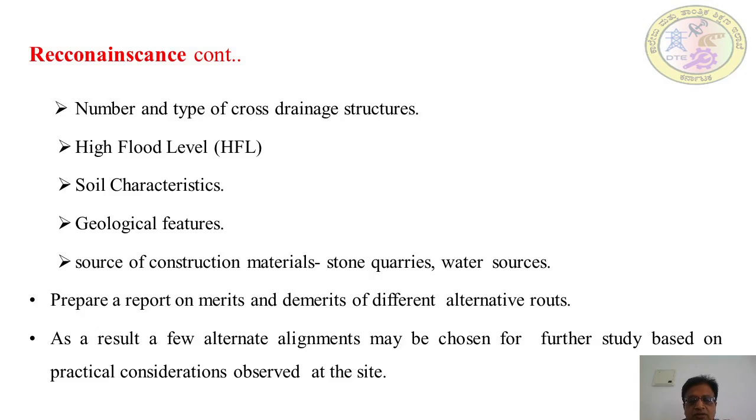Whatever the material that you use for the highway, it should be available at a nearby distance, so that the transportation cost you can reduce. So for that purpose, you need to identify the stone quarries. Not only the stone quarries, you need to identify the soil quarry also.